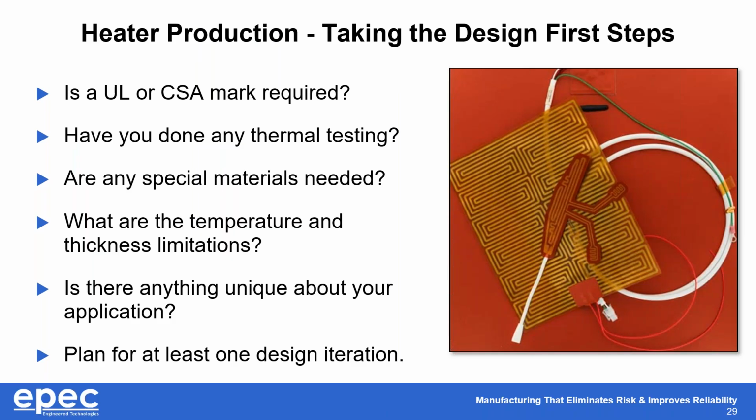We want to know early if there's any specialty materials involved, whether you need a low outgassing PSA or a specialty foam that has a certain thickness, or if it's an off-the-shelf connector with a 20-week lead time. These are important for us to do our evaluation, both at the initial design phase, as well as any product safety recommendations we would make.